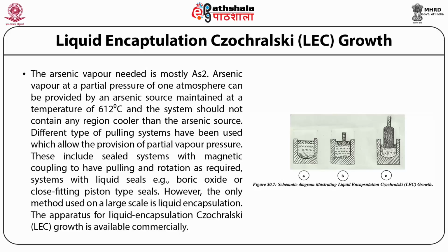These include sealed systems with magnetic coupling to have pulling and rotation as required. Systems with liquid seals, for example, boric oxide or close-fitting piston-type seals. However, the only method used on a large scale is liquid encapsulation. The apparatus for liquid encapsulation Czochralski, abbreviated as LEC growth, is available commercially.